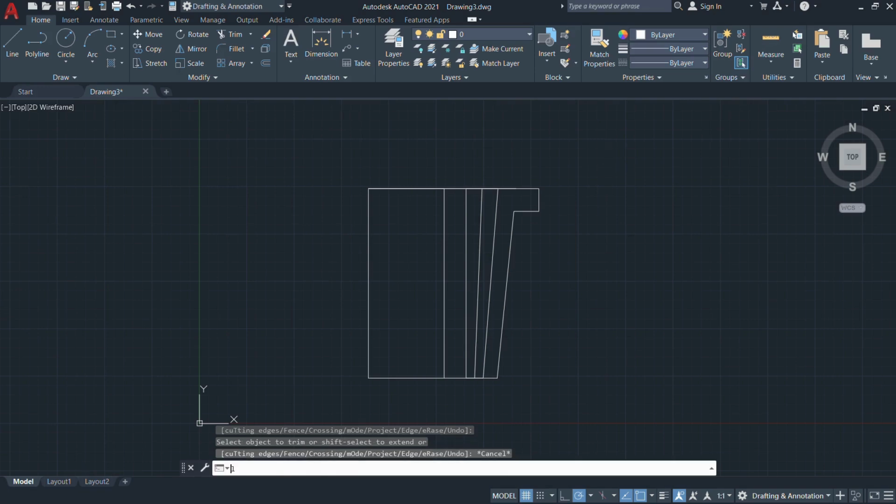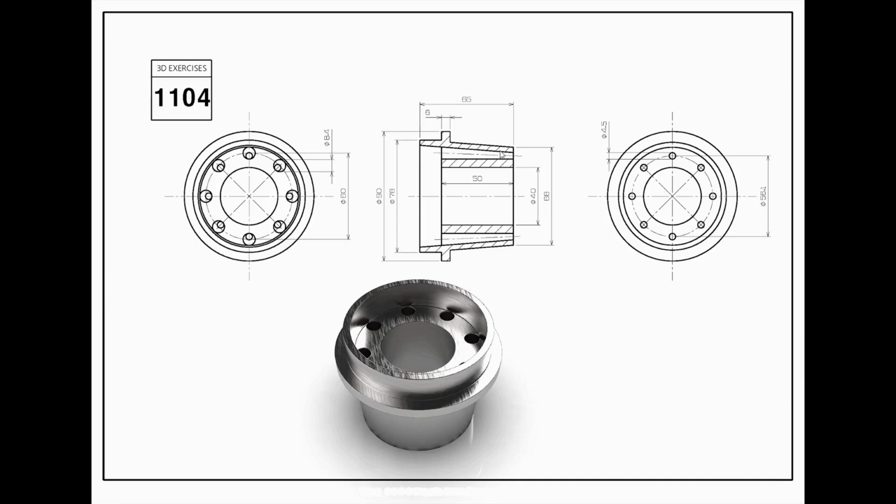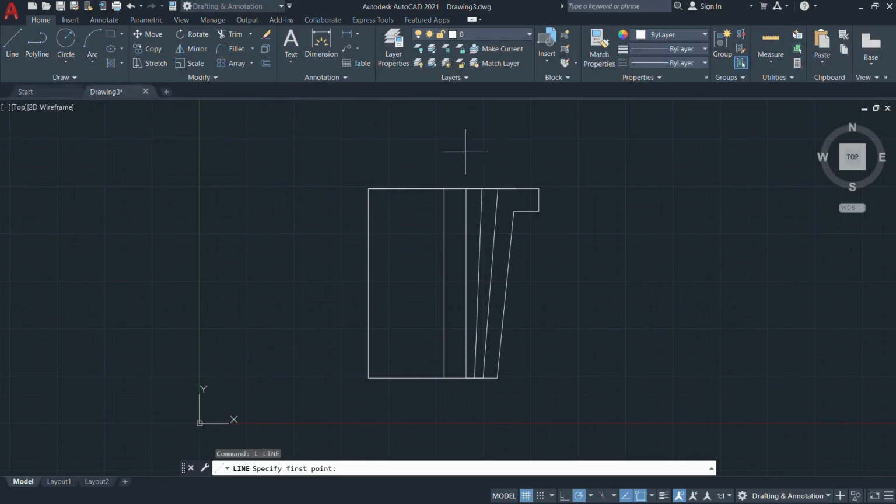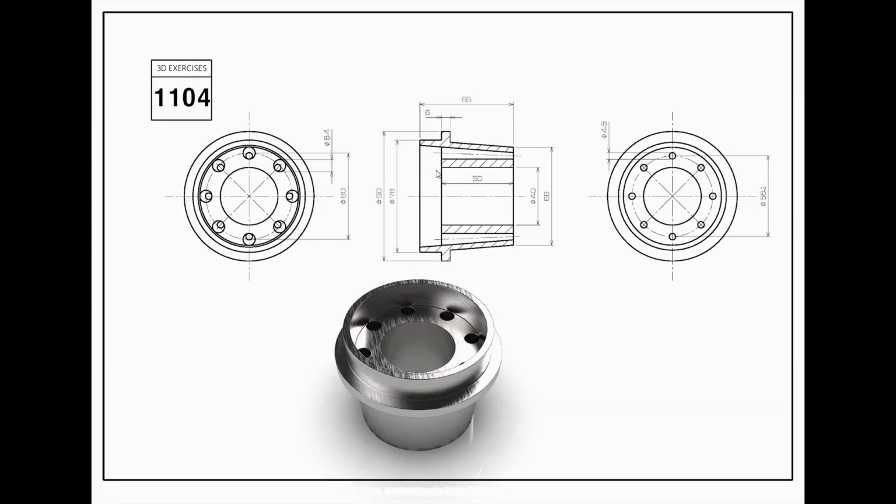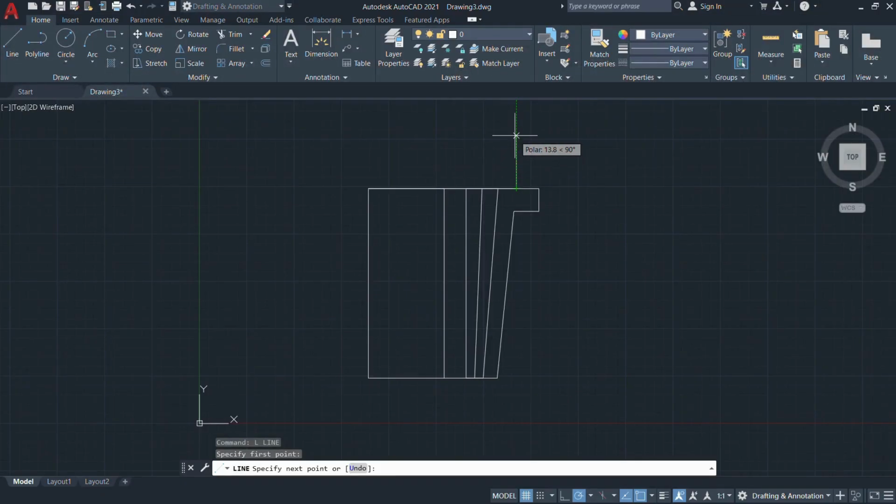Okay, once we draw a profile, next again choose a line from its area. We already drew a reference line up to the distance of 39 mm. From the endpoint, I am going to draw one vertical line profile. The overall height is 65 mm. The initial zone is 50 mm, and the rest of the portion is only 15 mm. So just draw only 15 mm of line profile vertically.